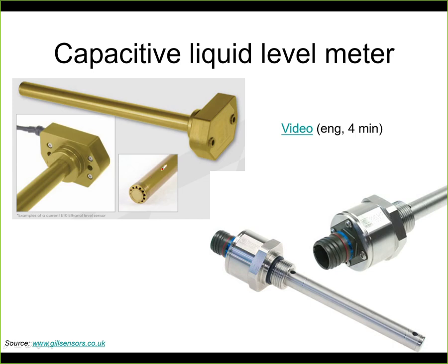So this tube is the second electrode and this is the first electrode, and the liquid will enter into the sensor with those holes. It will fill the sensor, so it will go all the way to the liquid level, and you will evaluate the capacity of it. So this is inside of the tank, and this is outside of the tank. So this is the electronic circuit, or just some terminal box that allows you to connect all this together.